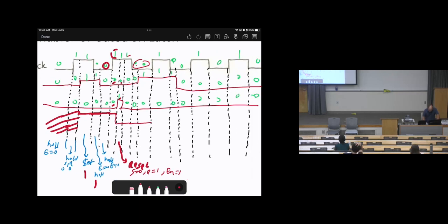Then you will see here, clock becomes 1, then look here at S equal 1, then it will go to set. So you see something maybe kind of weird. There's an update happening here, but it will not be reflected here. Why? Because the enable button was off. So even though the enable button was off and the switch was on, it didn't do the update. Okay? So let me erase this.